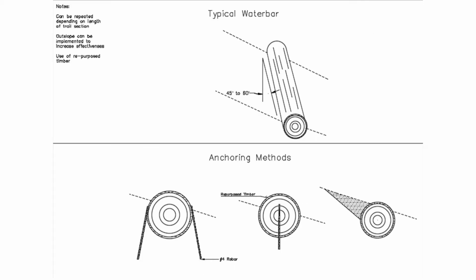We presented to the town of Manchester 3 alternatives for water erosion control: a water bar, a French drain, and a drainage dip. Because there are numerous different types of areas where there is trail erosion, it was concluded that all 3 alternatives will be useful, so we created design plans for each. This is the final design plans for the water bar. This will be implemented at all 3 typical areas.